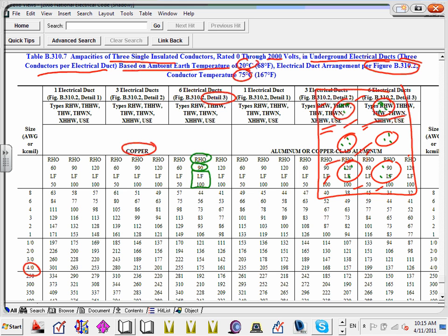Brad, where would you use a 50? If you have 4,000 amps and they have a tie, 4,000 amp here, 4,000 amp here, so you either energize from this or energize from this, but both cables are right next to each other. Then each one of them you put at 50, because based on the design, because it's a 4,000 amp tie, the tie and the main would never be energized at the same time. So that's where the 50 is.